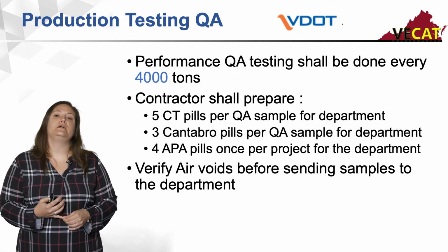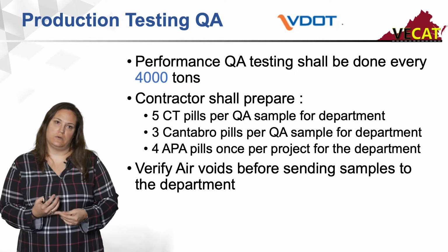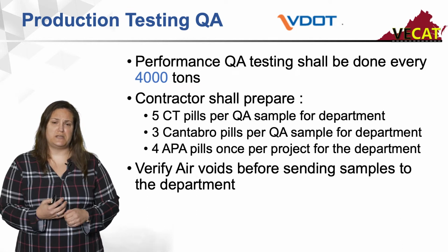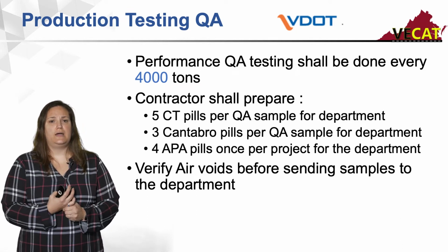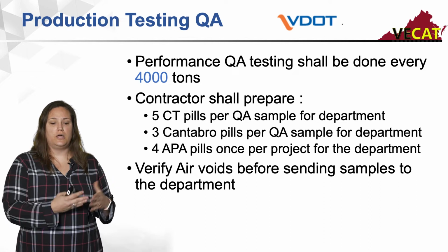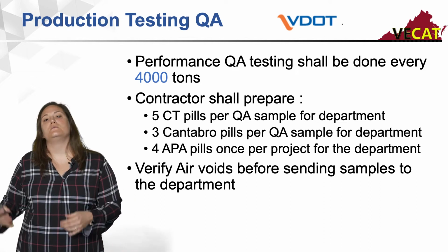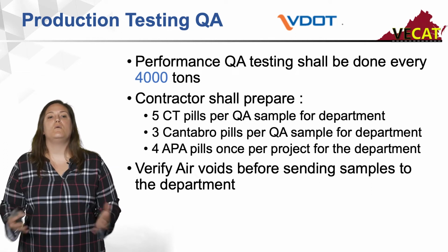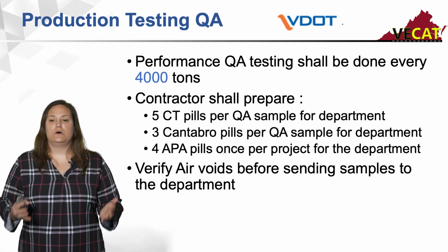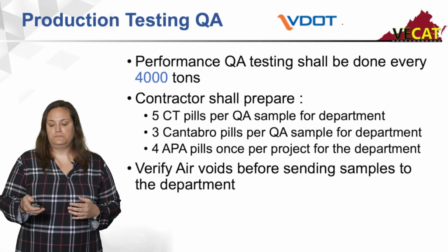Please verify your air voids before you send in your specimen samples, just so that if there's any variance, we already know what was done and that it was compacted to spec, and if there was some type of damage on the way, that we know that it was done, and so that we can just move on and note that.